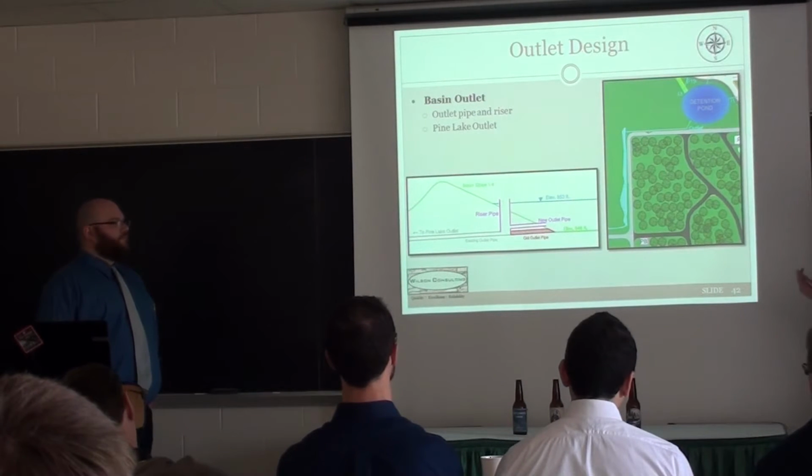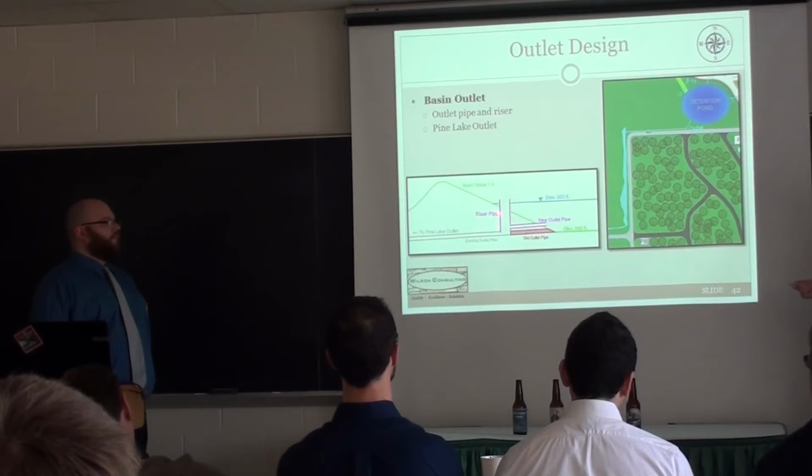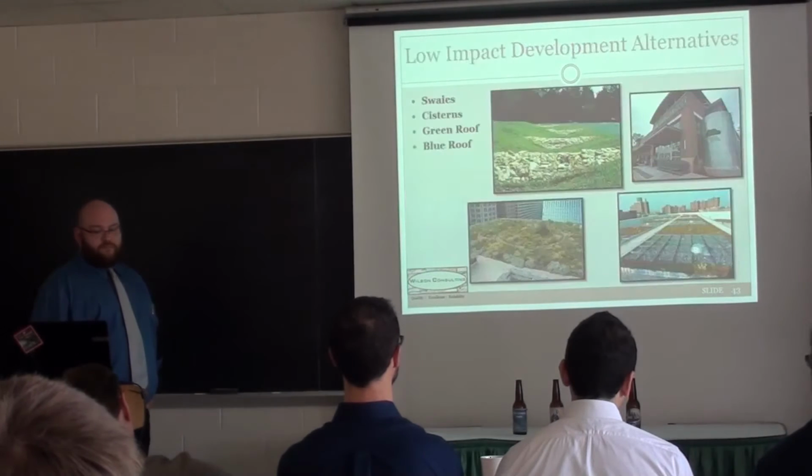So actually, the detention basin acts as a detention / first volume basin. We also incorporated a riser pipe so that if the water elevation does reach a certain elevation where there is a risk of the basin flooding in the area overflowing, water flowing over, it will instead go into the riser pipe, which will then be sent off-site.